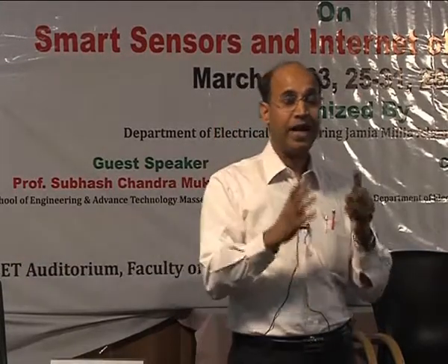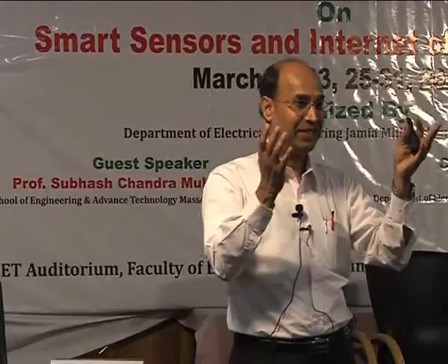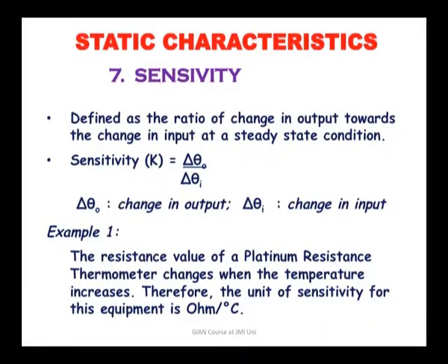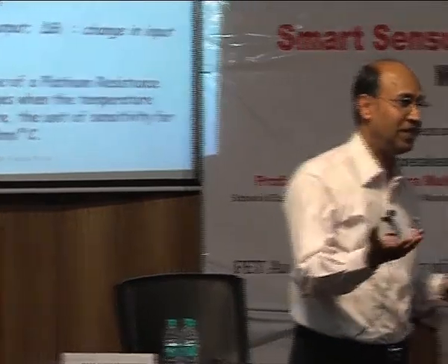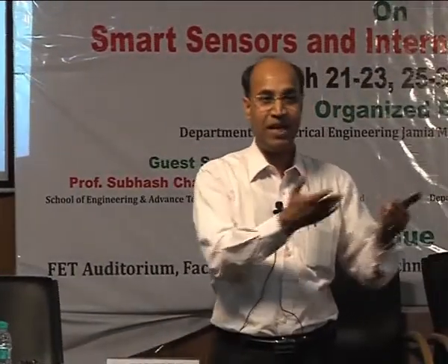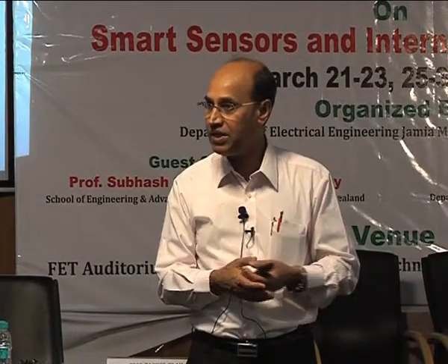So it's not that a temperature sensor will be sensitive only to temperature. That's the ideal thing. You understand? We can say, oh, it does not really care. But in practice, it's not ideal, because it's dependent on the environment. You can change the temperature sensor signal due to the change of humidity, due to the change of pressure, due to the change of any other operating conditions.